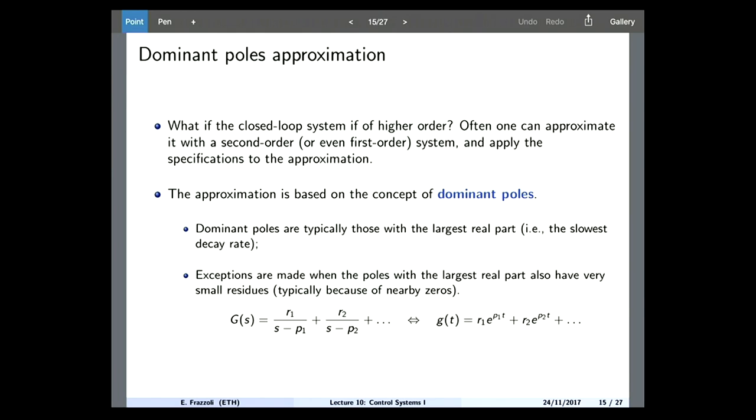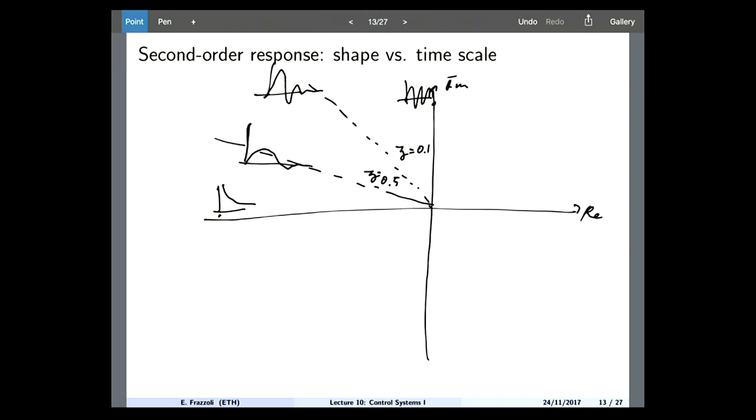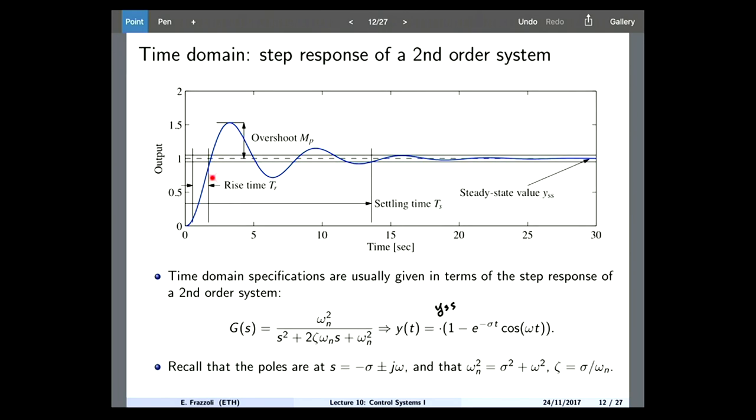Okay, so essentially, things to remember are, if I tell you that I want a percent overshoot of, say, 20%, a peak overshoot of 20%, really what I'm telling you is that I want a damping ratio of 0.7. Again, it's one of the things that people tell you in exams, or bosses who are particularly unfriendly to you, right? But there is no point in saying, I want a 20% overshoot. 20% overshoot just means damping ratio 0.7, period, okay?